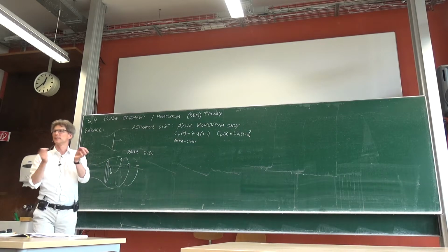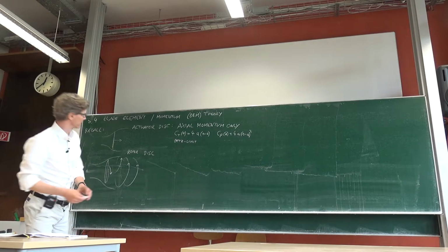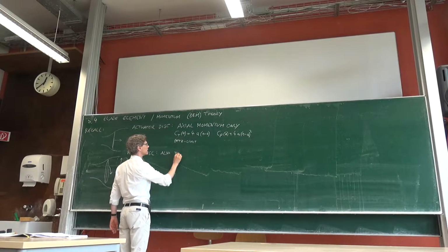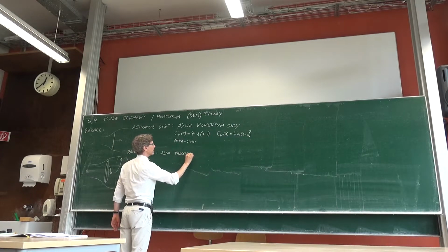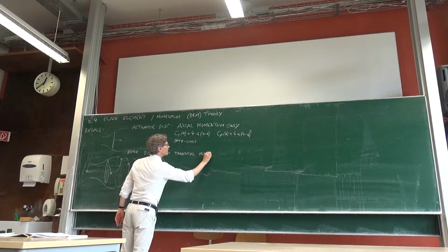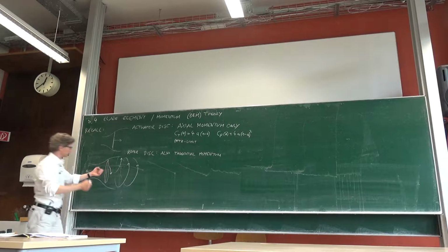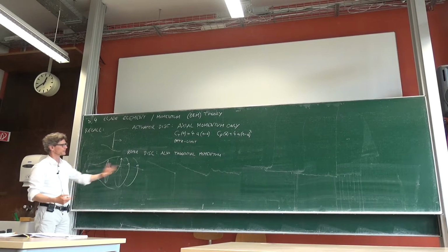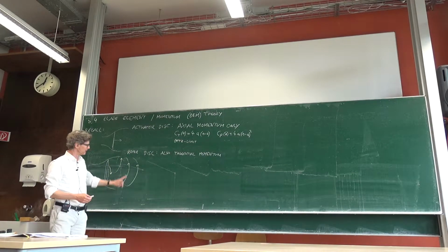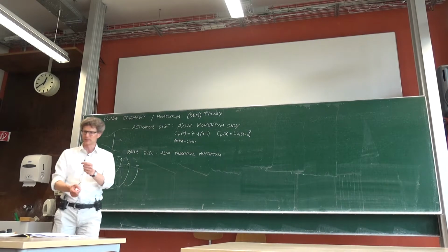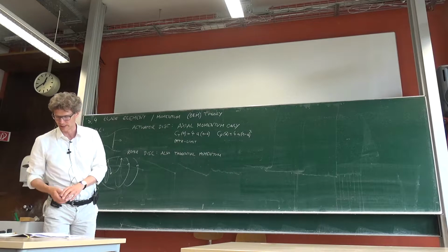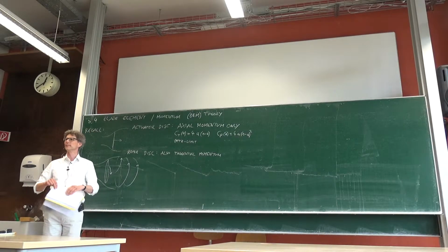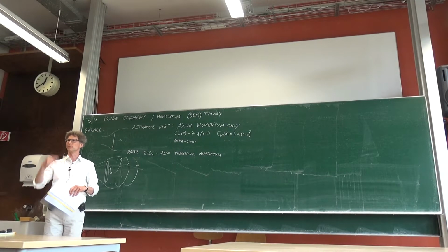Okay, so this is like how the wind moves after the wind turbine, because we get pushed in this direction. And by just comparing energy balances, we could also derive one thing. So in addition to axial momentum, we also get tangential momentum. And the reasoning was very simple. If we want to get this disk turned, then there must be some change in momentum in the airflow, and this is what we assumed here. And if we look at the tangential velocity of the airflow, it will be different at different radial locations. But we derived a formula, and I think, did I introduce the tangential induction factor already? A prime? Yeah, okay, great.